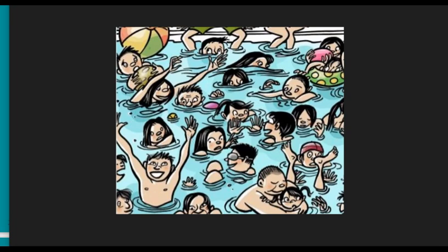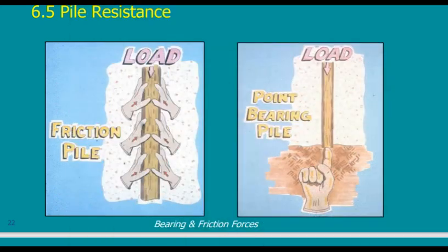This is exactly what happens in piles. The end bearing will still be the same. If, instead of having this one pile, you have next to it three or four piles, the end bearing will be working very well. But the friction, how can I say that the soil next to my pile is carrying the pile and I have another pile next to it and the same soil is carrying it? It means that the soil, instead of carrying one pile, started carrying all the piles around it. So the efficiency of these piles has decreased.